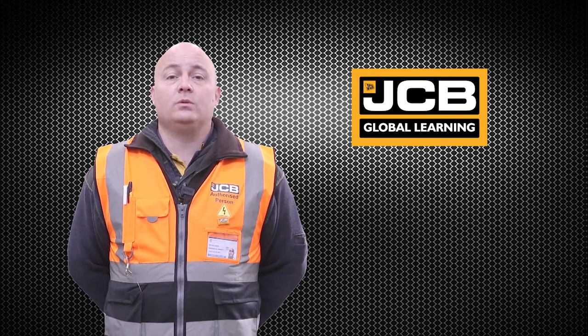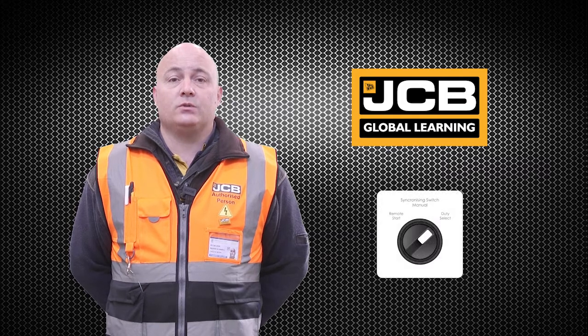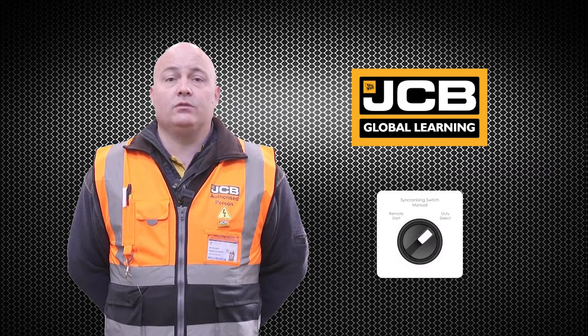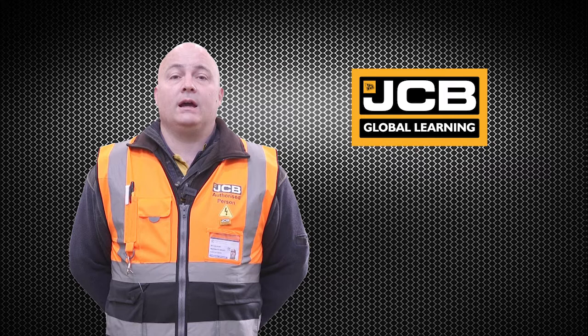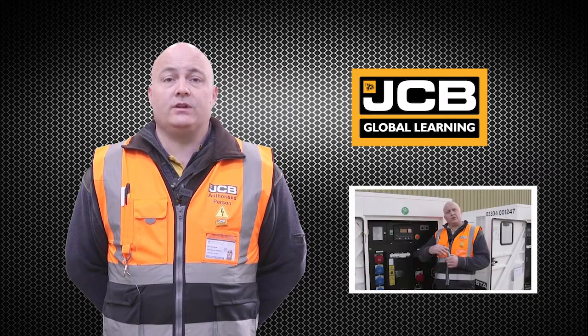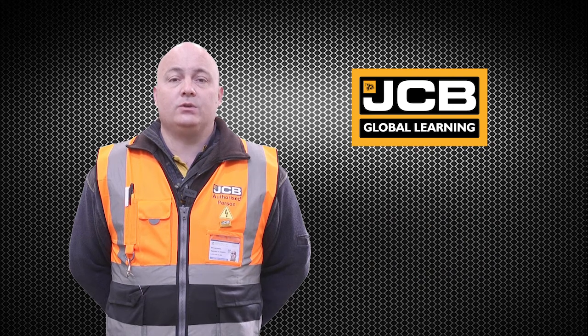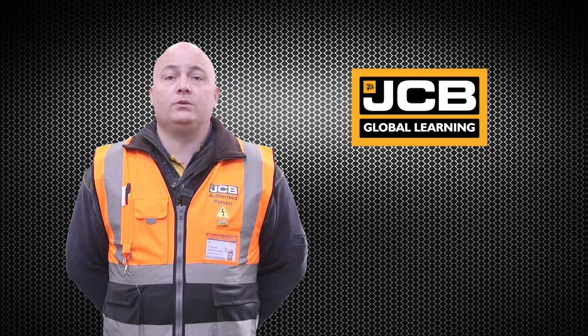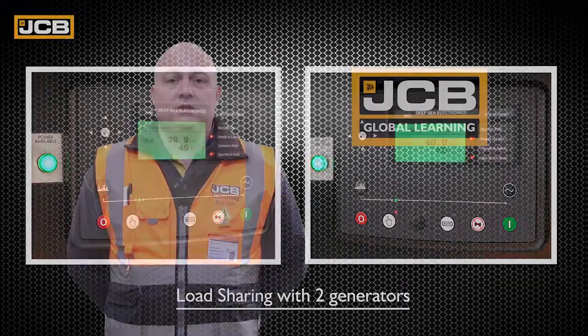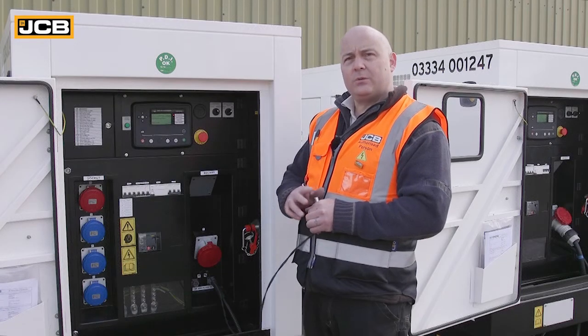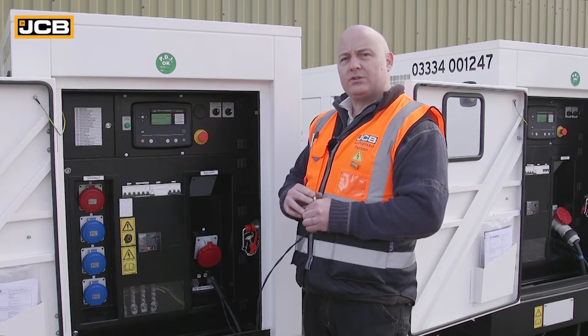And in today's video, we'll look at the synchronized switch to understand what position that needs to be in for the remote start, how to connect the remote start switch to the generators, what impact the remote start switch will have when it's closed connection and open connection, and how to view the load sharing between all the generators in the synchronized sets.